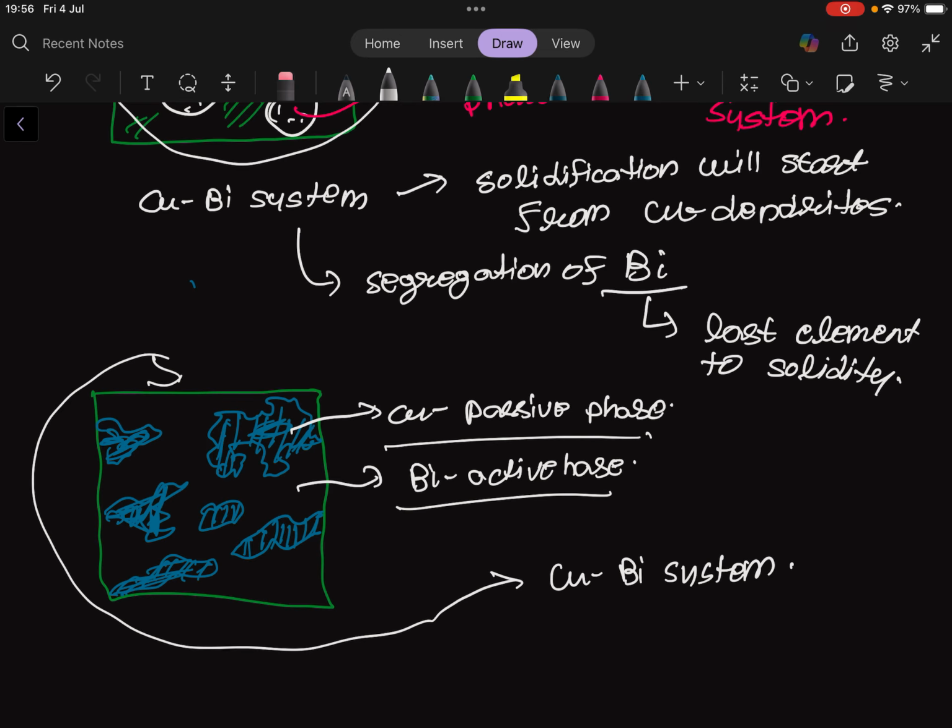If bismuth is melting, it's not stable. It will leak everywhere. The nice thing is that bismuth has good wettability on copper. So we can use this material as PCM. The PCM is able to stay stable even if the bismuth is melted, simply because of good wettability.